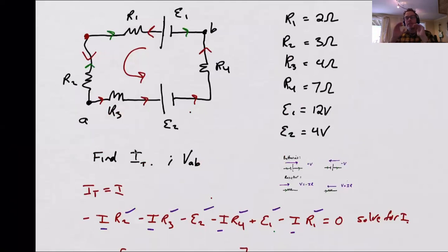Right now, I'm going to say, since we assumed the current in this one, what if we assume the current went a different way? Do we generate the same result? Or if not, how does it compare to the other one? And remember, we said that the magnitudes are going to have to match. So ignore those red tick marks on this circuit. We're going to assume the current, if we're starting from the top left, is flowing to the right, those arrows in green. Again, though, I get to choose which way I want to analyze the circuit.